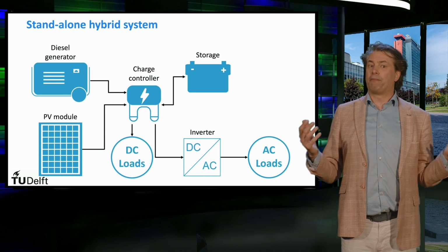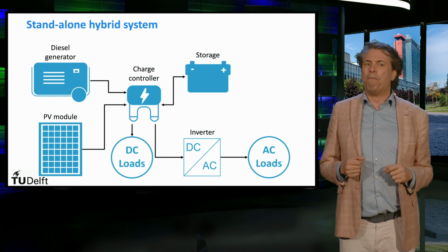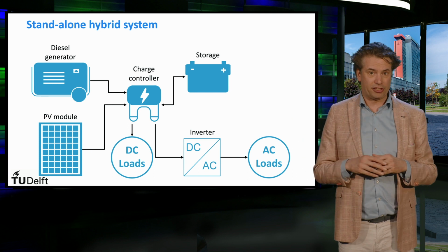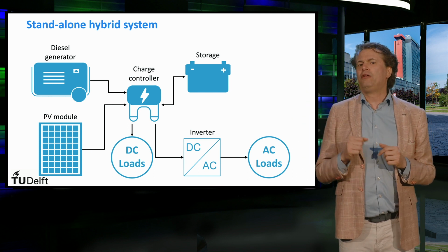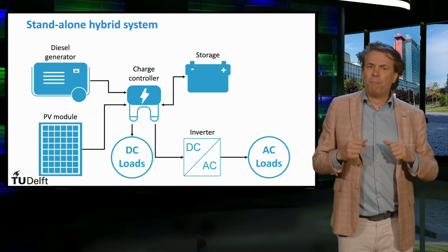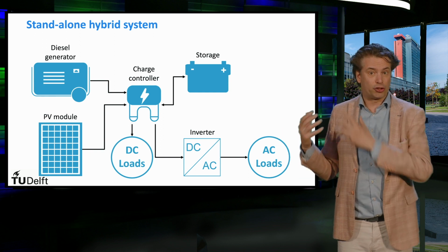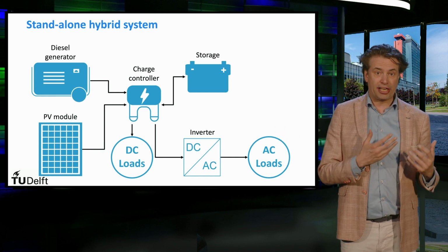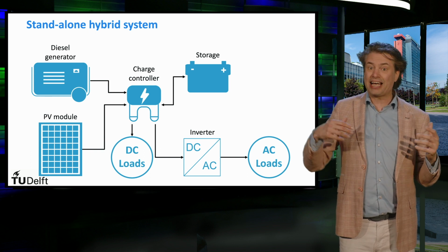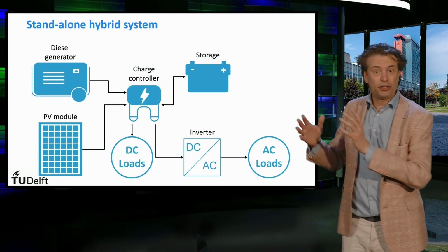To optimize the different methods of electricity generations, hybrid systems typically require more sophisticated controls than standalone or grid-connected PV systems. For example, in case of a PV diesel system, the diesel engine must be activated when the battery reaches a given discharge level and stopped when an adequate charging state is reached. Therefore, the diesel generator works as a backup, which can be used to recharge batteries or to supply directly the load.